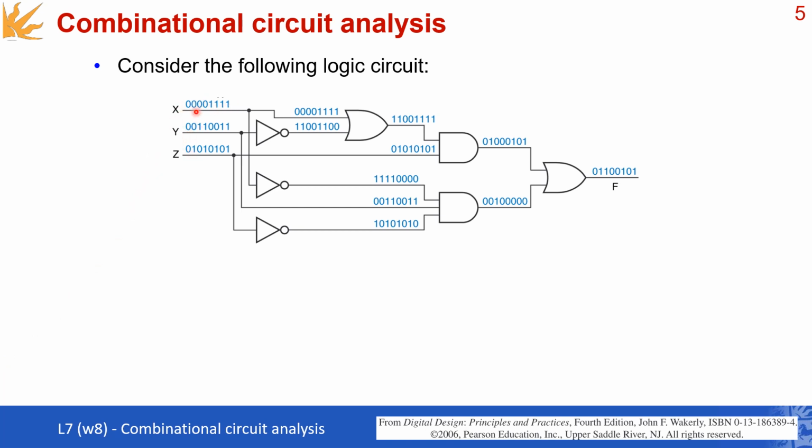If you read the values vertically of the 3 inputs, then you will realize that the first input is 0, 0, 0. The second one is 0, 0, 1, which stands for number 1 in decimal. Then you got 0, 1, 0, which stands for 2. And as you read them all, you will go through all the numbers from 0, 1, 2, then 3, and all the way to 7, which is in binary 1, 1, 1. So these are all the possible combinations of input you can give.